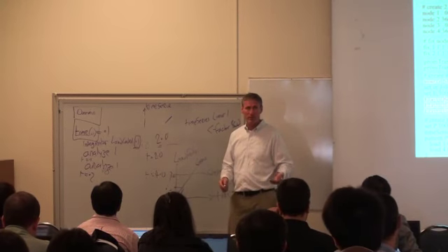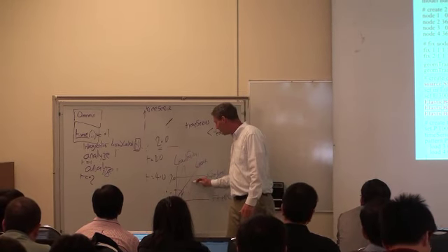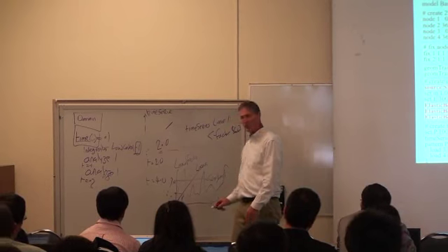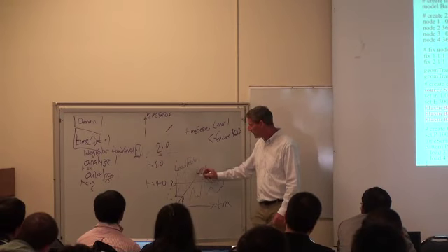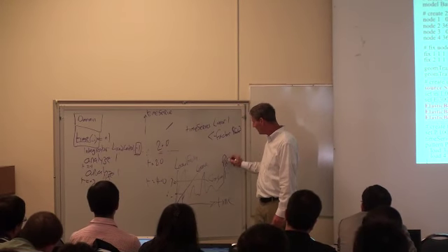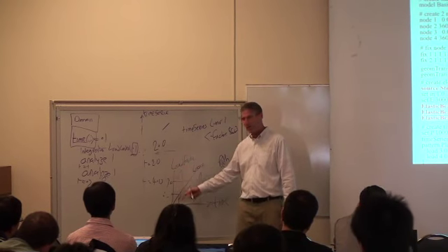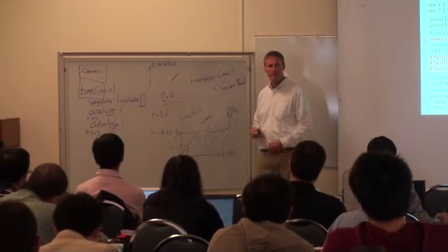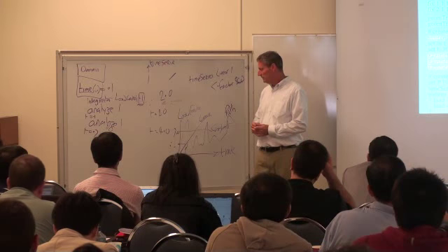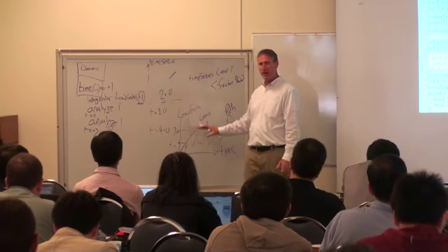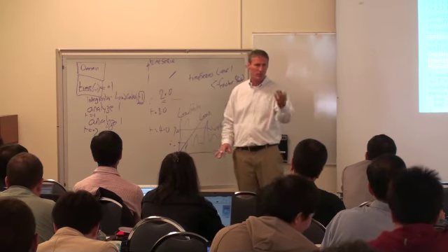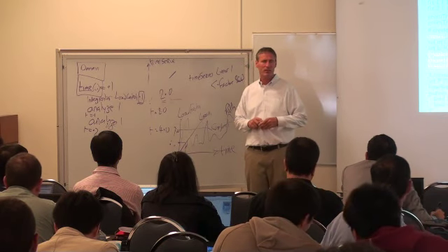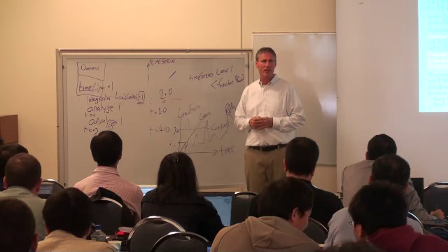And then the path one that we can do is, you specify whatever the time, this is like a path. Whatever the time is, the load factor is totally changing. Okay? So we can actually use the path inside a load pattern to use a multi-support excitation. That would include multi-support excitation.